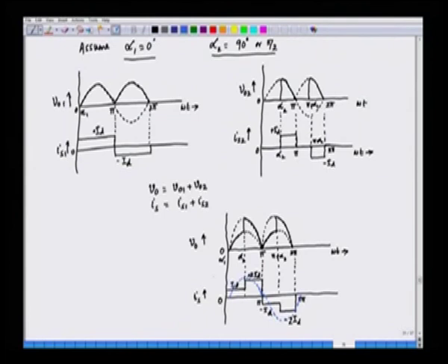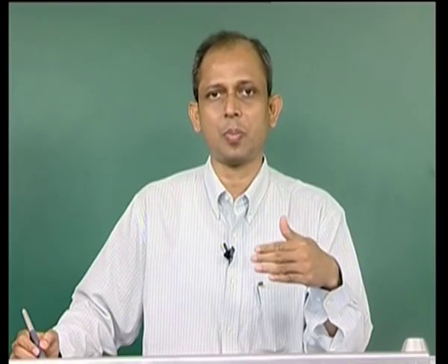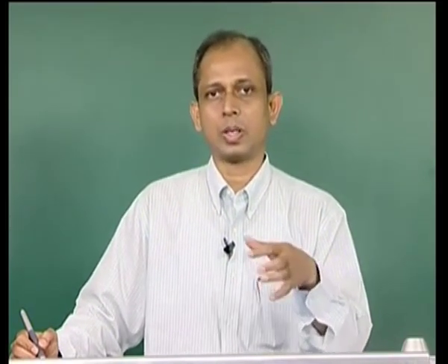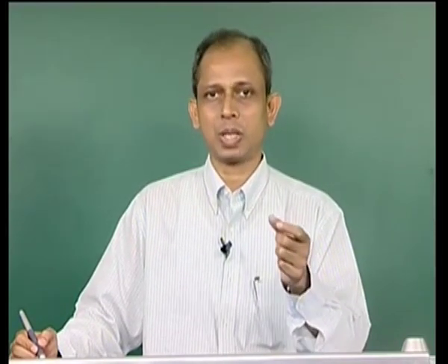So, this could be IS1, the fundamental component of this IS. So, when we operate this converter in sequence control, the input power factor improves, or the input current lags behind the voltage by a lesser angle, which means the displacement factor of the input current is better. Now, this can also be proven mathematically.